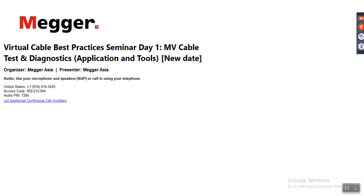So that is the reason why VLF 0.1 Hertz has very high accuracy and is reliable to test the cable. It has been proven anyway. Don't worry about that.